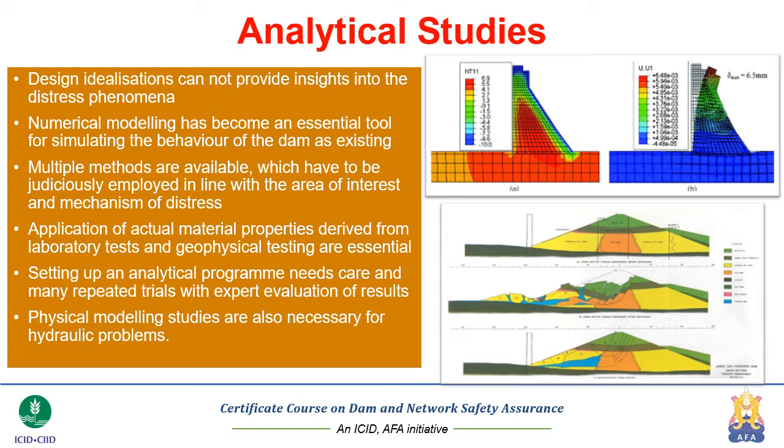So design procedures may not be able to provide insight into the distress phenomena straight away. There may be some additional insights necessary. The designs have been generally developed on the basis of certain very simplifying assumptions. For example, the assumption that the dam is a rigid structure, the foundation is also rigid, and that way a concrete dam will behave like one rigid block sitting on the other rigid block, or an earth dam in which the slips are supposed to occur in a particular manner under a slip circle kind of analysis. So these idealizations may not remain valid when there are variations in the densities of the dam within the body, or when there are certain other phenomena.